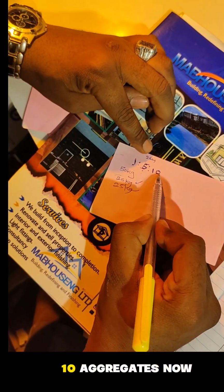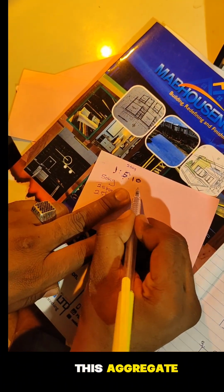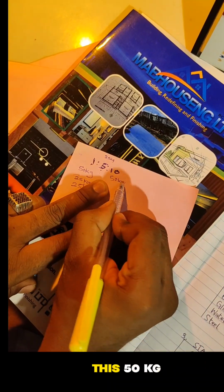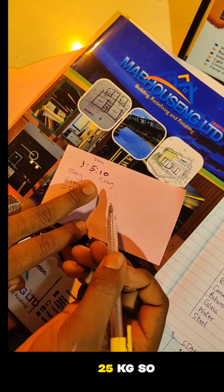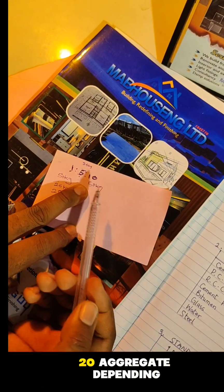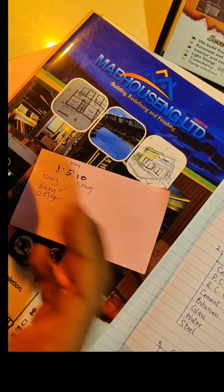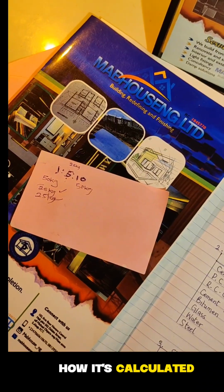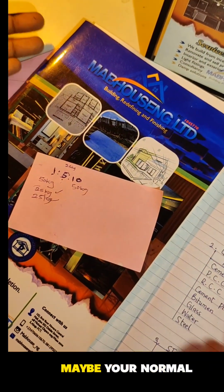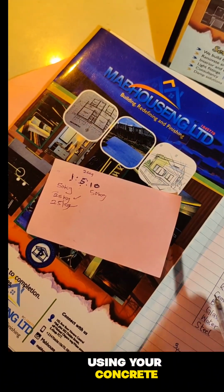Then for this 10 aggregate, this is 50 kg too each. For this 50 kg, our head pan is 25 kg. So you multiply it. You need around 20 head pans of aggregate, depending on the size of your aggregates. So that is how it's calculated basically. And this is for your normal concrete mix ratio using your concrete machine.